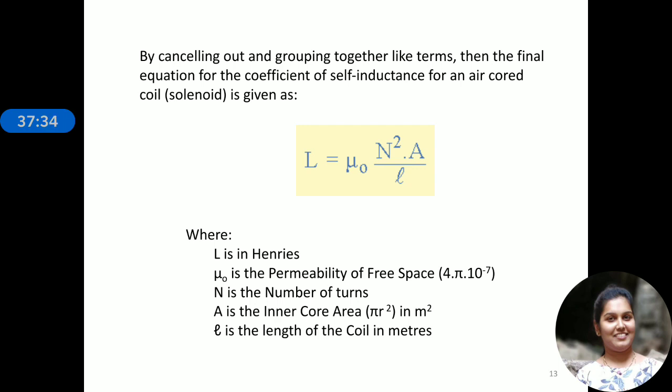In both cases more wire is required to construct the coil, and therefore more lines of force exist to produce more magnetic flux, or more EMF will be produced, right? So if you take a thick wire or if you increase the length of the wire, more EMF will be induced. So thereby self inductance will be induced.